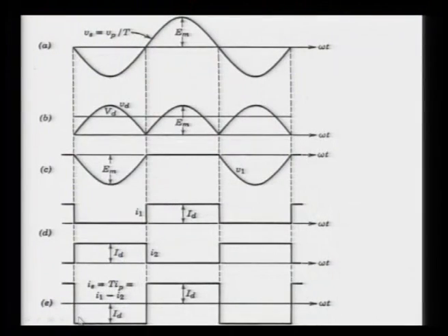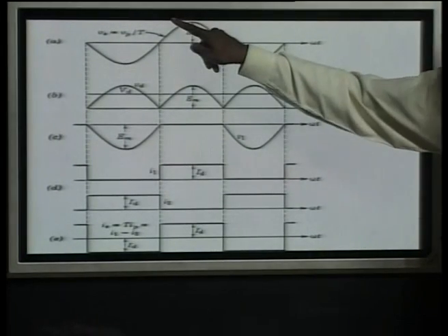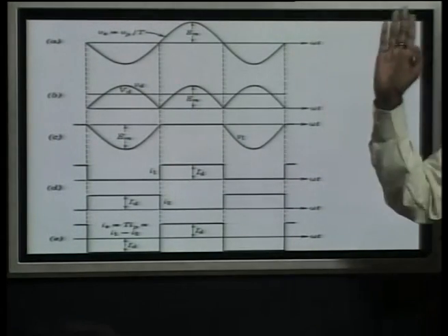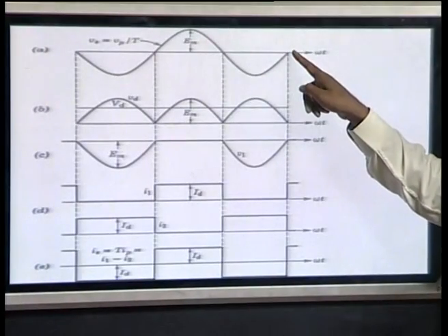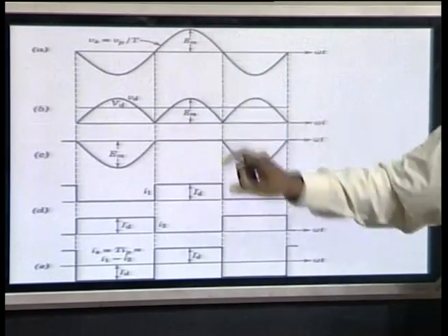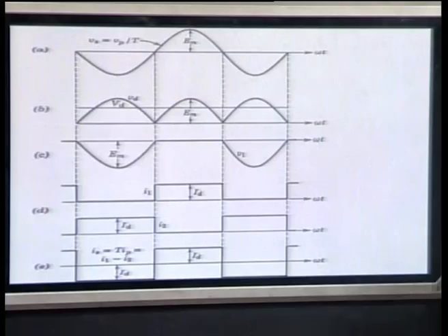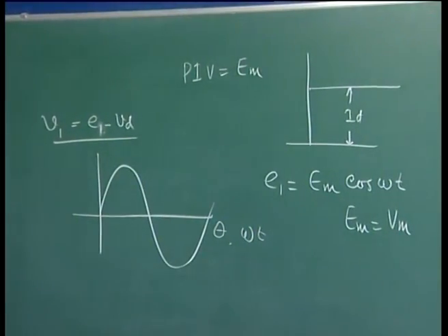To see here again this wave shape, now this is your secondary voltage that is appearing. I am assuming this as the 0 axis, because it is continuously changing, you can have your axis anywhere. So, you are just taking here the sinusoidal voltage of one cycle. Now, taking this as the 0 axis, you are getting, let us suppose, Em sin omega t, that is appearing in the secondary of this bridge rectifier.